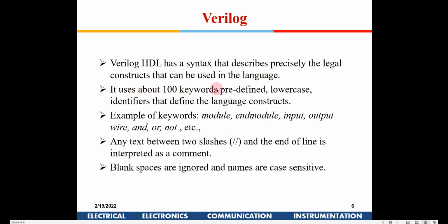There are several keywords there, so you don't have to remember everything. There are about 100 keywords which are predefined. They're all in lower case. For example, module is the start of a module, endmodule, input, output, wire, and, or, not. As we keep moving forward, we will understand the meaning of each of these keywords also.